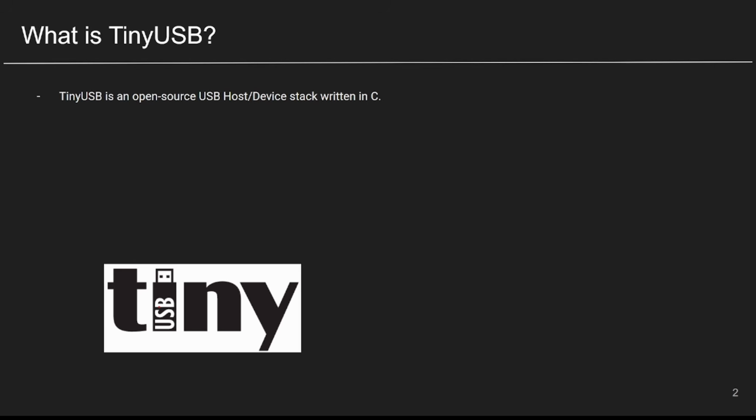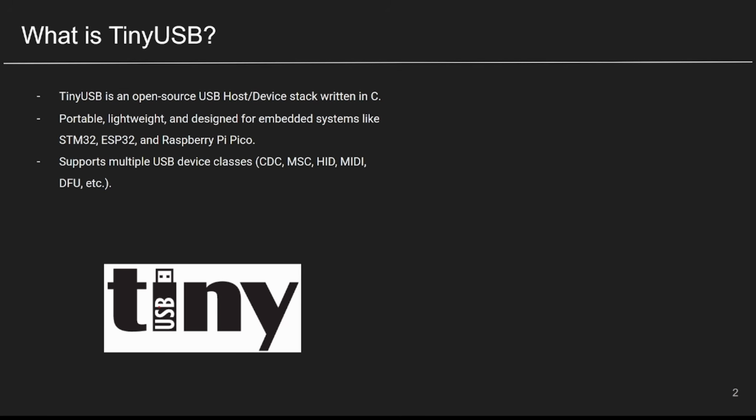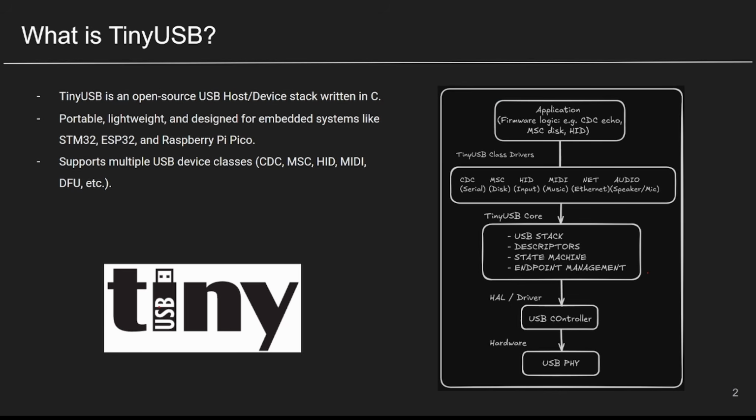So what is TinyUSB? It's an open source USB stack written in C and supported by Adafruit. It's lightweight, portable, and tailor-made for embedded devices like STM32, ESP32, Pico, etc. It has support for various device classes like CDC for serial communication, MSC for mass storage, HID, MIDI, etc.